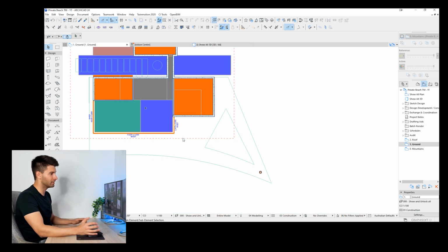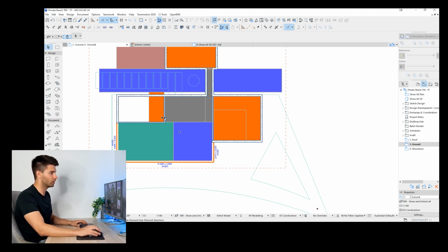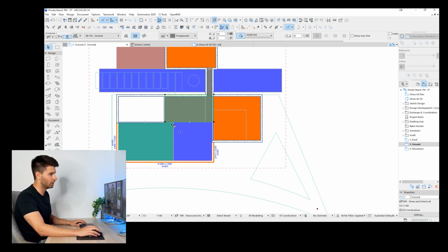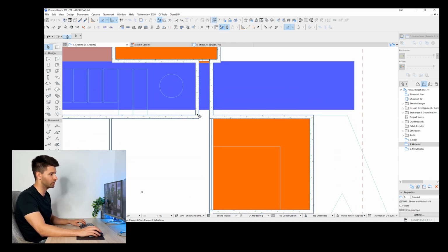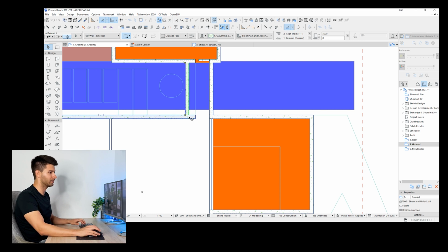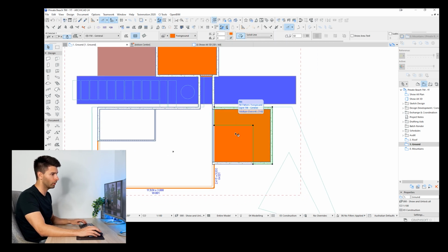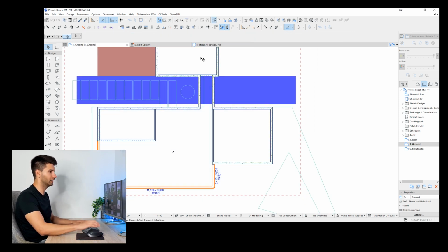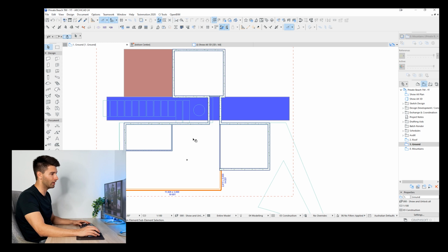Now going back into ArchiCAD, we can continue developing the interior of our property. So we know that this is going to be a bedroom, we don't need that. We know that that's going to be part of the bedroom. That's the kitchen, that's the living, that's the dining, and that is the hallway we have here. The hallway gives us 600 mil wide, which is nowhere near enough. So we'll extend that another 600 millimeters and connect these two elements to be able to actually walk in that space and recenter that landscaping strip. So we already know where all of our spaces are going. We know what we're doing internally, so we can get rid of those elements there and we can continue working on the rest of the design.